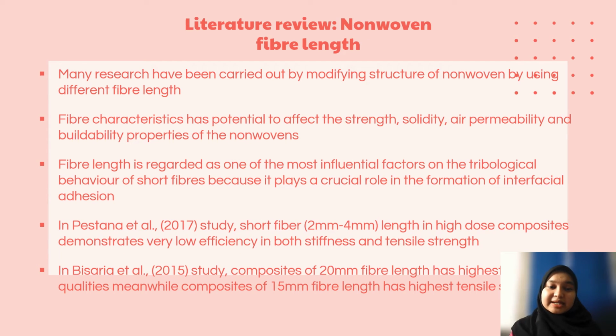Many research have been carried out by modifying structure of nonwoven by using different fiber length. Technically, the length of the fiber is a crucial component of the raw material used in the manufacturing of nonwoven web because fiber characteristics have the potential to affect the strength, solidity, permeability and wovenability properties of the nonwoven. The fiber length is regarded as one of the most influential factors on the tribological behavior of short fiber because it plays a crucial role in formation of interfacial adhesion.